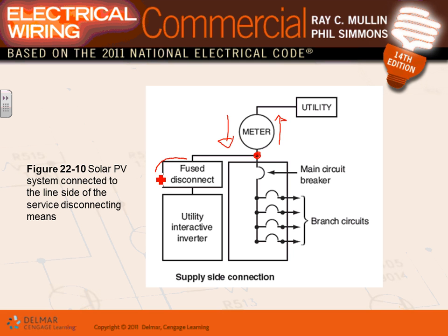You need to have a fused disconnect put inside. You have to label. So all these have to be labeled. Also, you have to label at the disconnect. You have to have a label right here at the disconnect that says photovoltaic system exists. Another source of power exists.